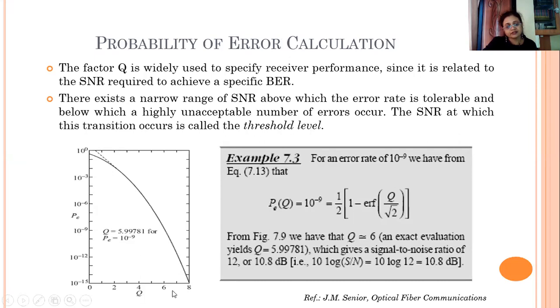And this is where you will see the quality factor depending on this, the bit error rate is calculated. Now, as I told you, for optical communication system, over so many years of observation, the value which is set by the telecom, this optical regulatory system, is 10 raised to minus 9.